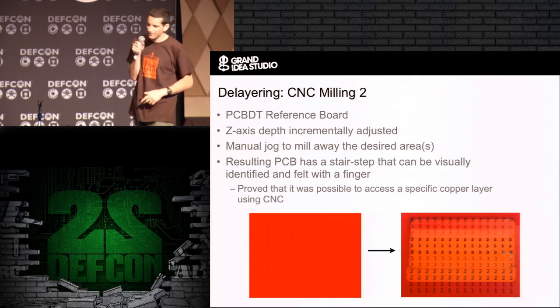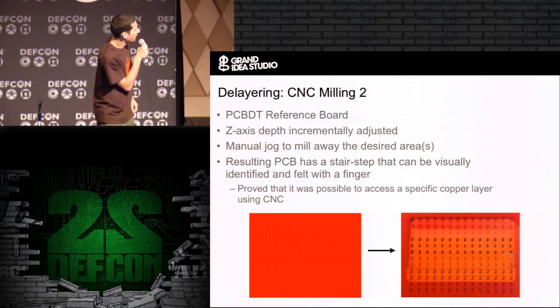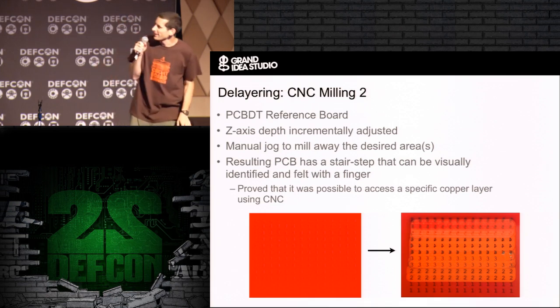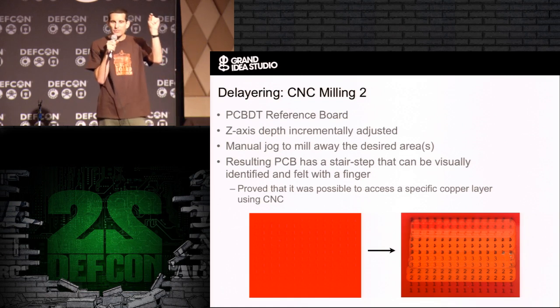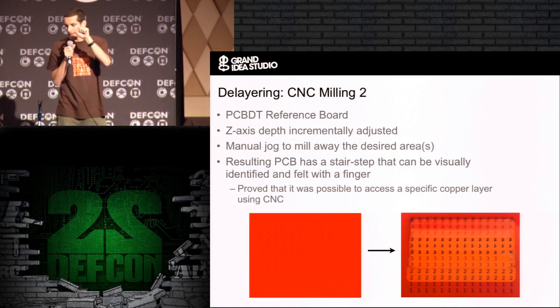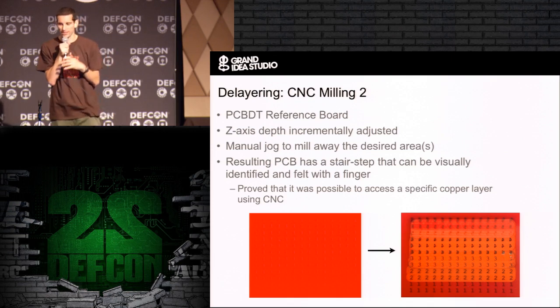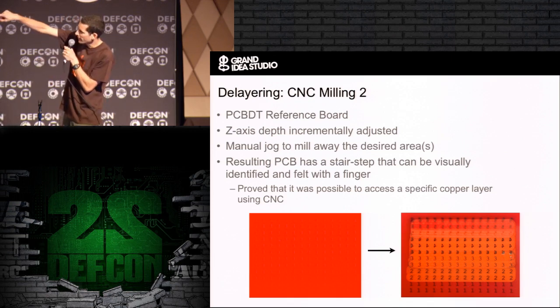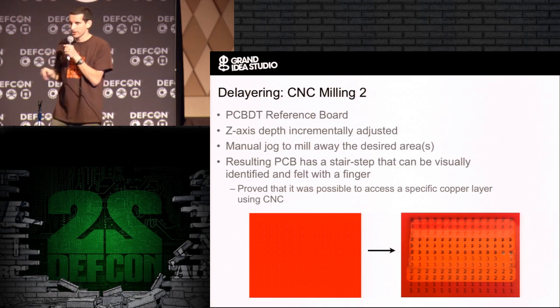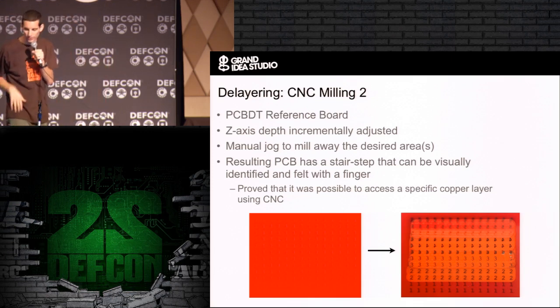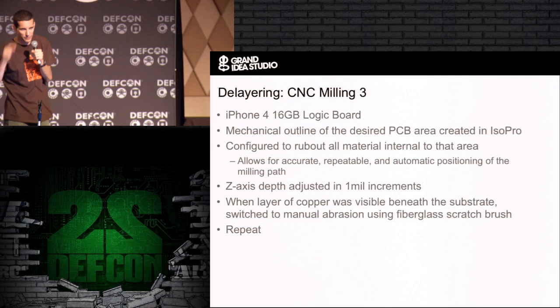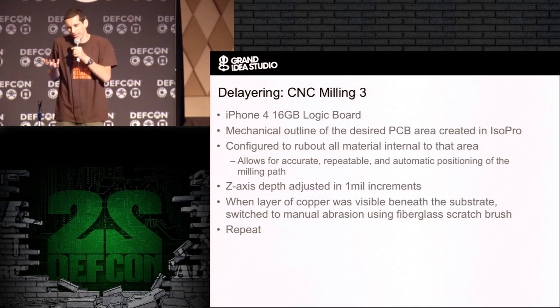This particular board, you can't really see the left image at all, or the right one really. But the left one has a bunch of numbers for the different layers. So layers 1 through 6 are all numbered. What I did is just went down and for each layer exposed those numbers, so I could prove, okay, now I can access layers 1 through 6. That was no problem. But that was a board with very thick interlayer spacing, so it was sort of like cheating.